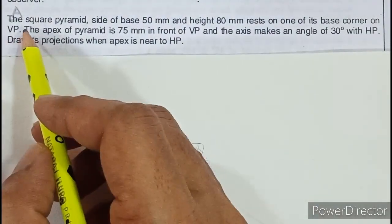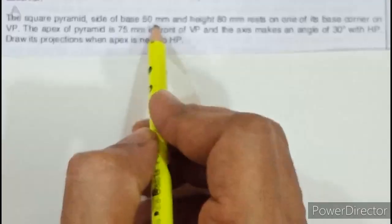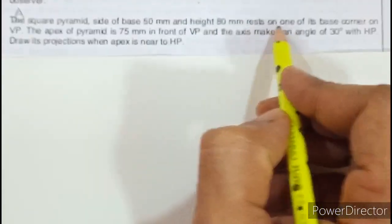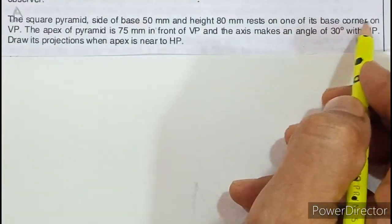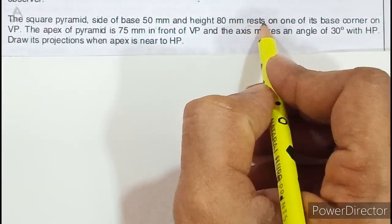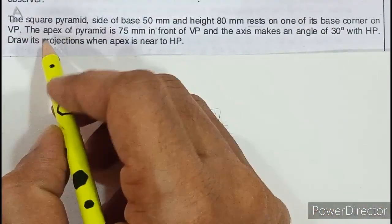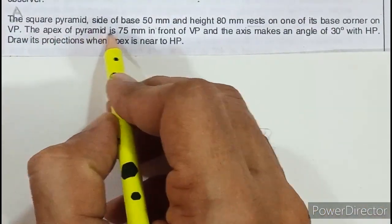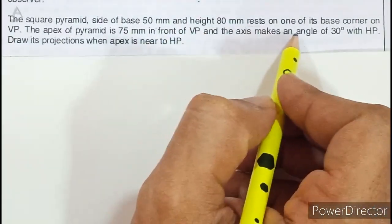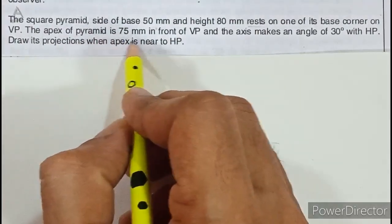The third question in projection of solids is a square pyramid, side of base 50 mm and height 80 millimeter, rest on one of its base corner on VP. So this word rest is an indication that it is the first stage. The apex of the pyramid is 75 millimeter in front of VP and the axis makes an angle of 30 degrees with HP. Draw its projection when apex is near to HP.